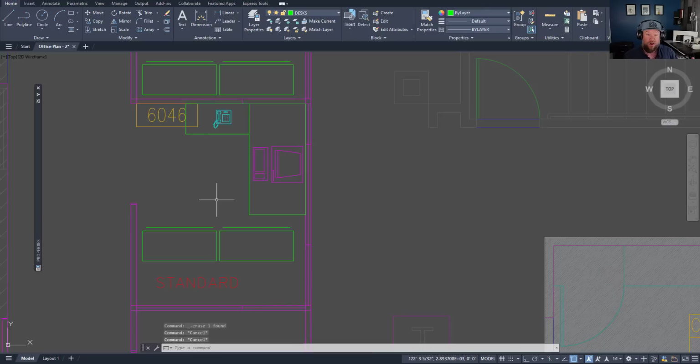So onto our next command and tool, and that is using Control and H to activate and deactivate groups instantly within AutoCAD. This one's a huge time saver, especially if you're using groups within AutoCAD. I explained this in a video two weeks ago, so I'll put a link to that, or you can search it up on the channel. It's blocks versus groups, but basically a group is any amount of objects in AutoCAD selected, and then you group them together so that they move and act like one big object, but all of these individual blocks and objects are still in the drawing and on their own.